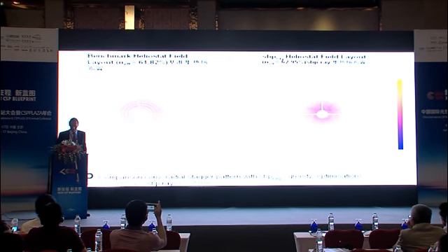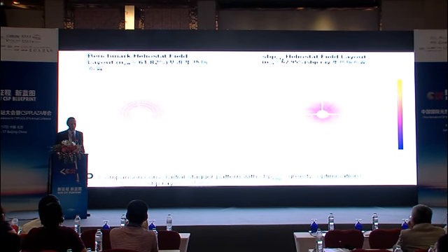But actually, if you use a method which we call the greedy optimization, where the heliostat itself is placed and then evaluated and optimized for its position, and the computer does it by itself, then you get something like 63% with exactly the same amount of heliostats, exactly the same amount of reflected area.